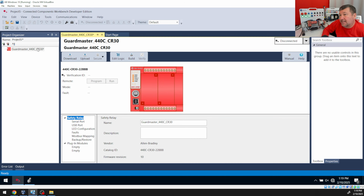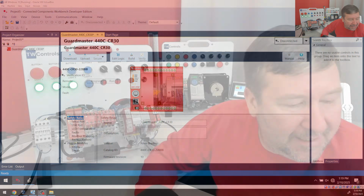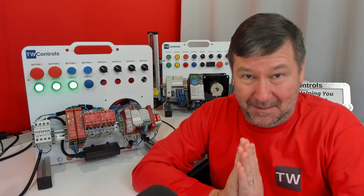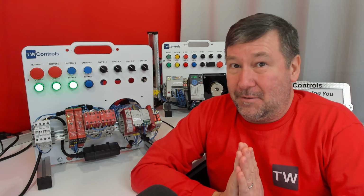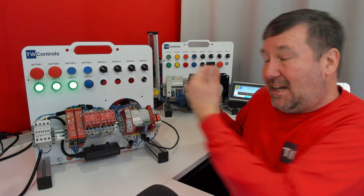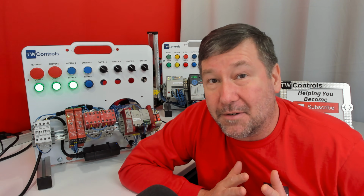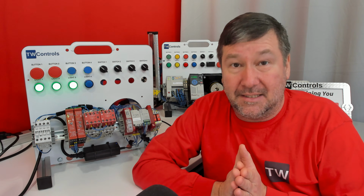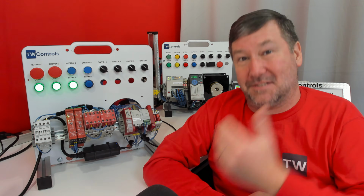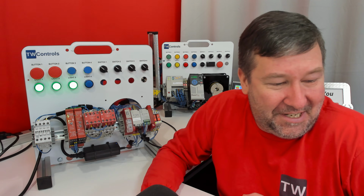We're going to double click on it, and now it is incredibly important that we understand the difference between upload and download. We upload from devices. We download to devices. It's the opposite of the internet, and I had somebody in my Part 2 class the other week say something I never thought of, but remember this: upload equals uptime, download equals downtime, because you're going to take your machine down.